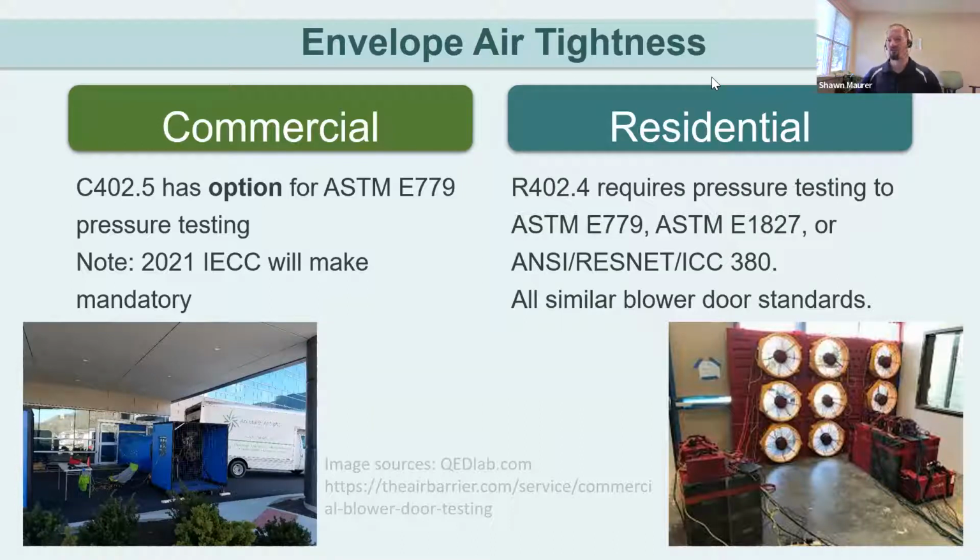Samples are required for the ground floor where you have entryways into the building. And if you have sub-levels that have exterior entryways, those would have to be tested as well. All floor areas underneath the roof, so top floors of buildings, generally will have to be tested. And then a 20% representative sample of the rest of the envelope. And as we touch on how we do testing later, you'll see how we can break the building up and do testing in different areas.